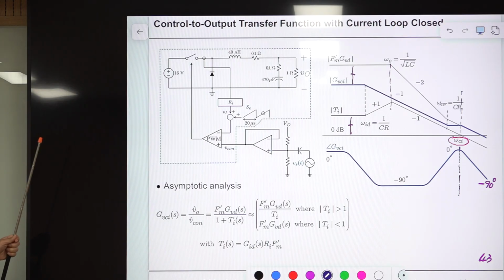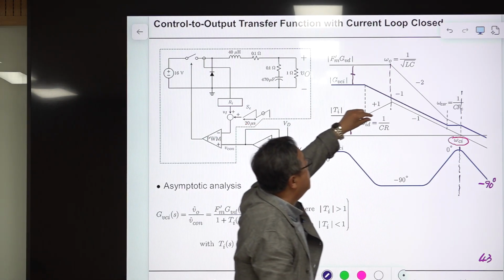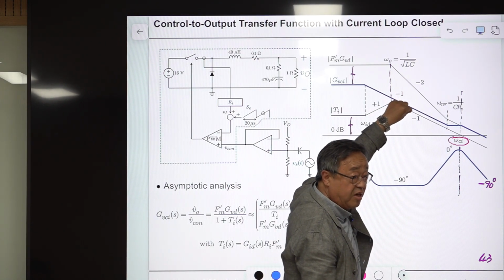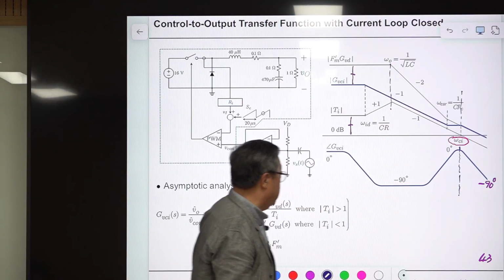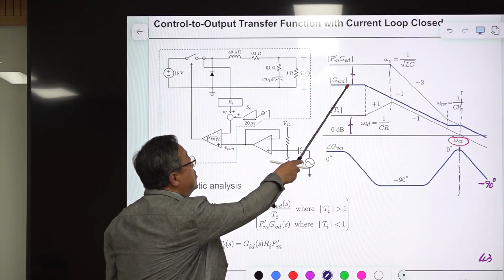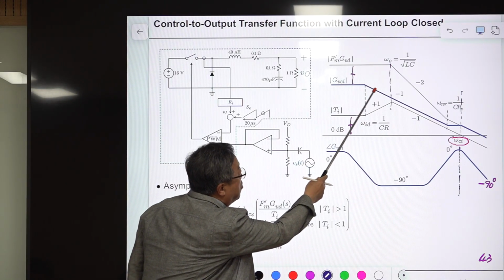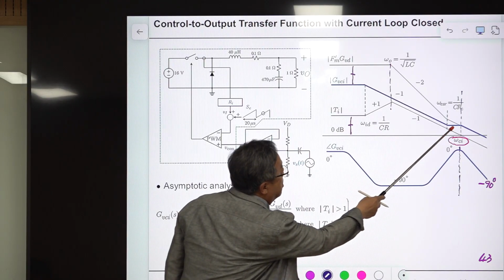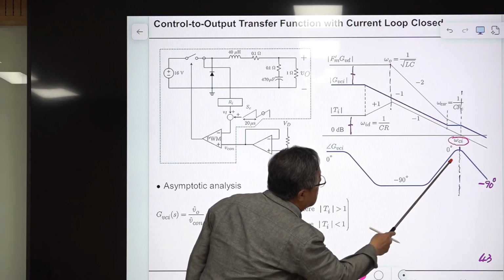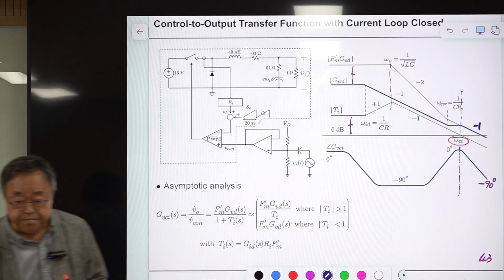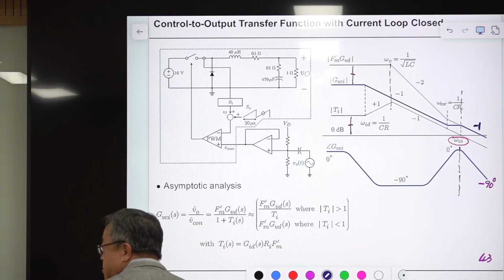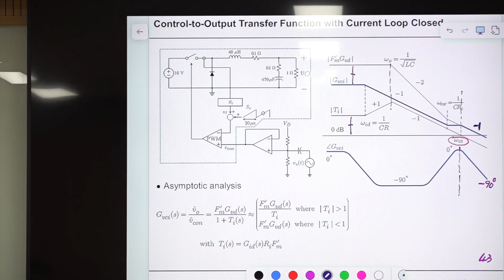Okay, you know how to do this. Right? Okay. And there is some distance between this and this. They don't have the same line. They're different because of this, determined by this length and so on. Okay? How about the phase? Phase is 0 here. This is the horizontal line, and the slope is -1. Then phase is -90, and in here, phase is 0, it increases to 0. This is -1 slope, phase becomes -90 degrees. Because this portion has -1 slope here, okay? -1 slope here. Okay? All right. So this is the way of generating this.